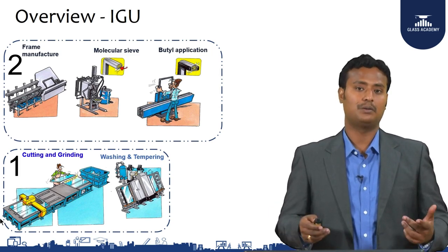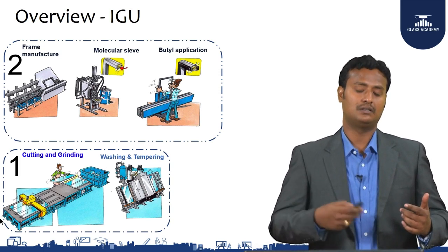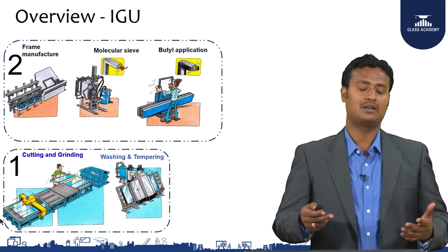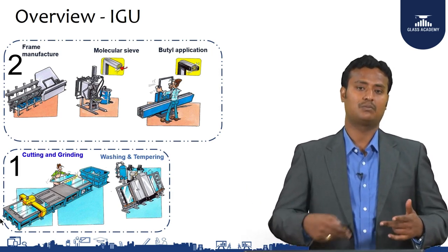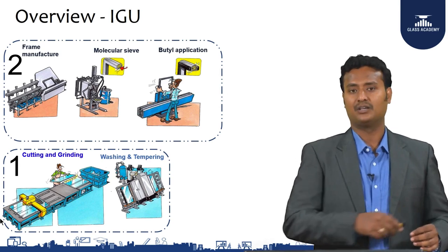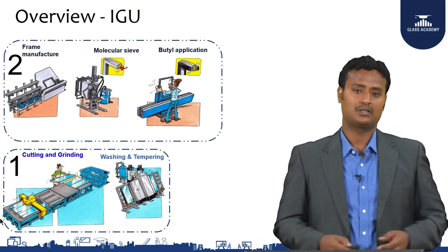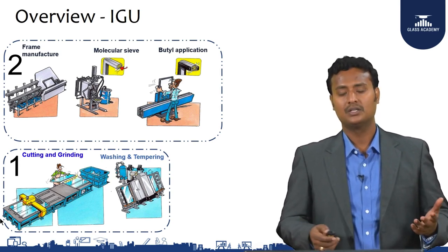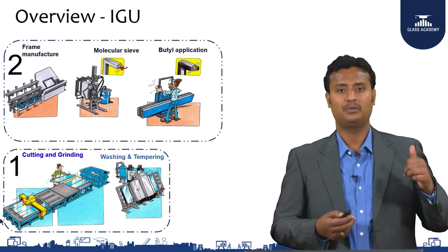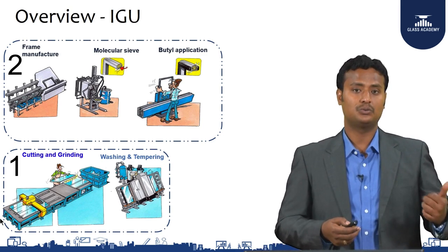Basically, there are two pumps and two nozzles dispensing the butyl, which is the primary sealant, through the two nozzles from one side to the other. When you take it out, it will be in a uniform form. You have to take it and gently keep it on the glass pane. We have to take a lot of precautions here, because our thumb marks, like fingerprints, should not be impressed on this primary sealant, because they will be see-through at the time of pressing.